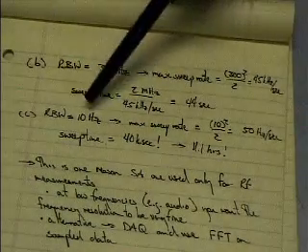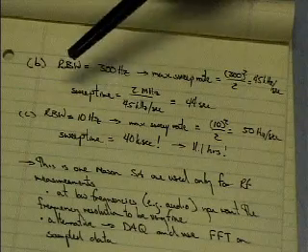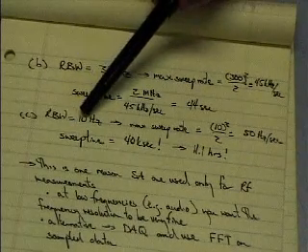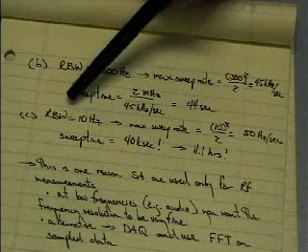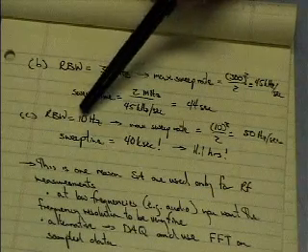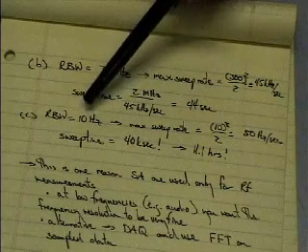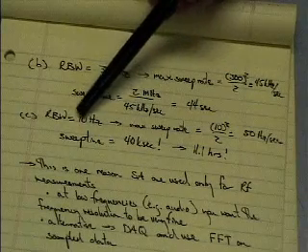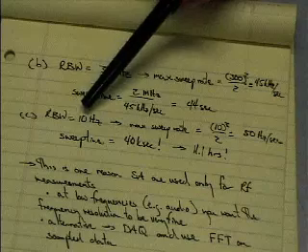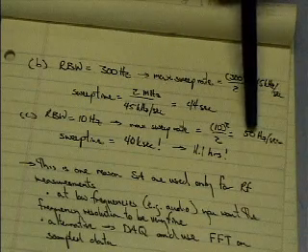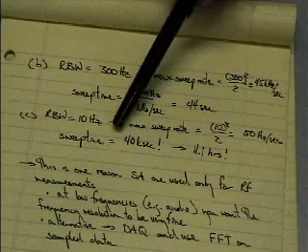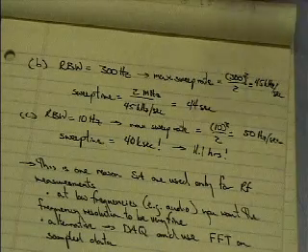Okay, well, let's say I just went on a bender and said, well, I want to be able to look at 10 hertz resolution. This is something that you may want to set up, for example, when doing audio signal processing. You'd like to be able to tell whether signals were within 10 hertz of each other. Well, this is going to allow us a maximum sweep rate of only 50 hertz per second, and if I'm trying to sweep 2 megahertz, it's going to be an 11-hour measurement.